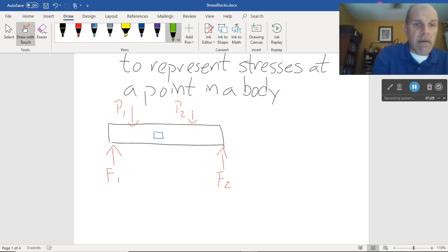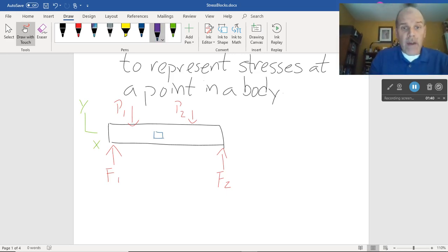The first thing to keep in mind, after I do what I always tell my students to do, and that is draw in your coordinate system. It's that important, yes, right? When we go looking for stresses, we need to be looking at internal forces. If we're looking at internal forces, we must be thinking in terms of a cut. Yes, a lot of times we'll draw a shear and moment diagram for this, but we have some kind of cut going through this, right?